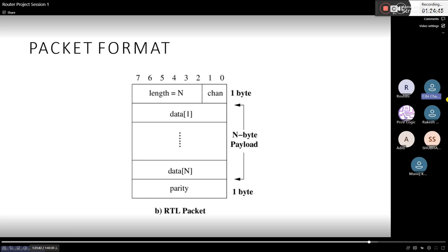You need not be confused that he said data and so the data will be transferred like that. In this project especially, we are going to play with packets only. Inside the packet we have data. That's why we are using a router here. See how compressed it is and how detailed it is. In a packet, we have which address we need to go to, what is the length of our payload, the payloads, and the parity also. That is why we say we need a router to avoid errors. This will be sent from source to a destination. Clear, or any confusion till now?